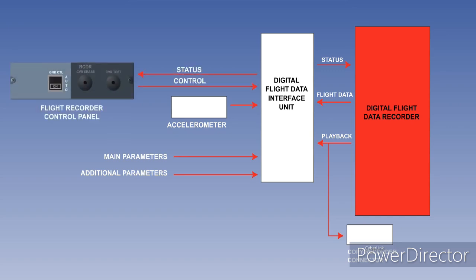In addition, there are 2 control panels. Firstly, the flight recorder control panel. This has a ground control switch which is latched in the auto position and will automatically turn the system on when airborne or on the ground with one engine running and for up to 5 minutes after engine shutdown. On selects the system on outside these parameters. The other control panel has an event marker switch which allows crews to mark an event for further investigation on return to base.